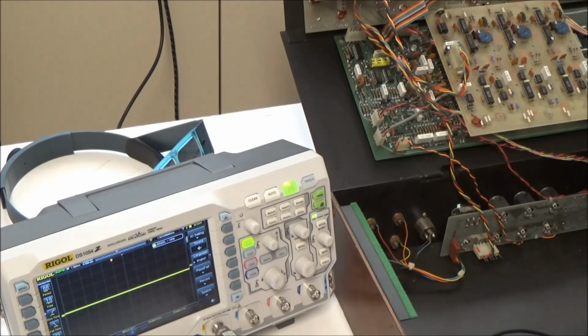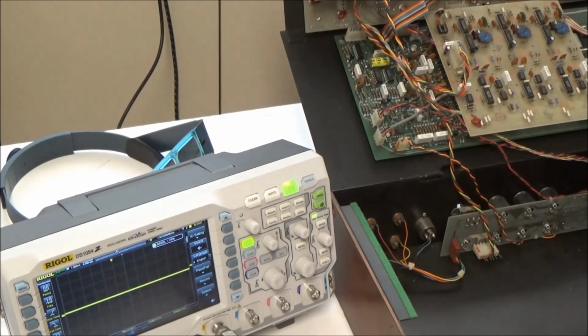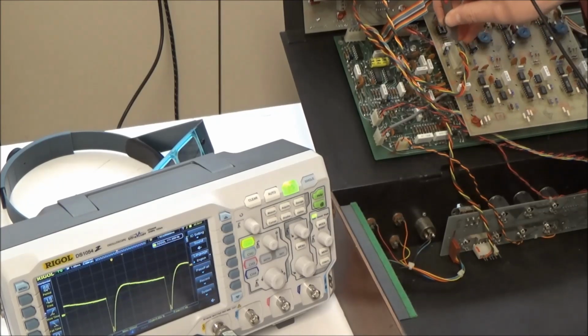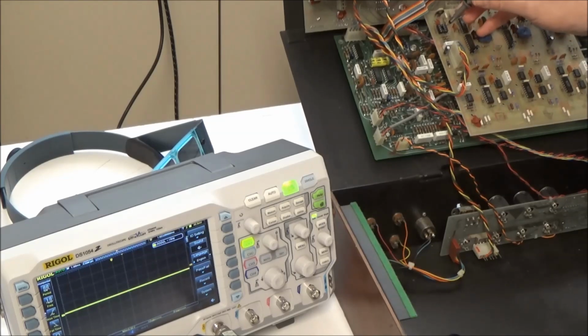And we can confirm this by pulling the op amp out completely. I know the circuit's powered and everything, but it's not going to hurt it. I mean, it kills the output to the synthesizer. But basically now we're going to go from this input signal to the non-inverting input of the op amp, which is no longer there.